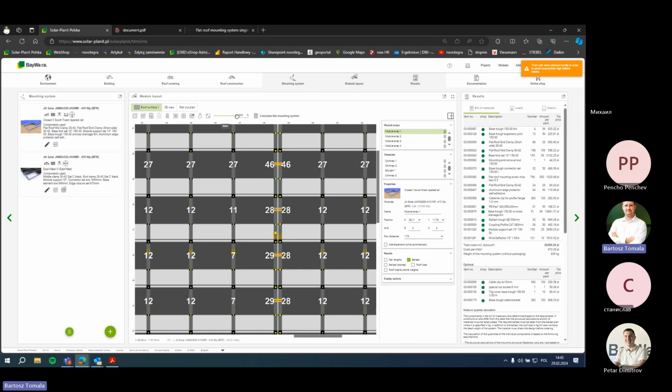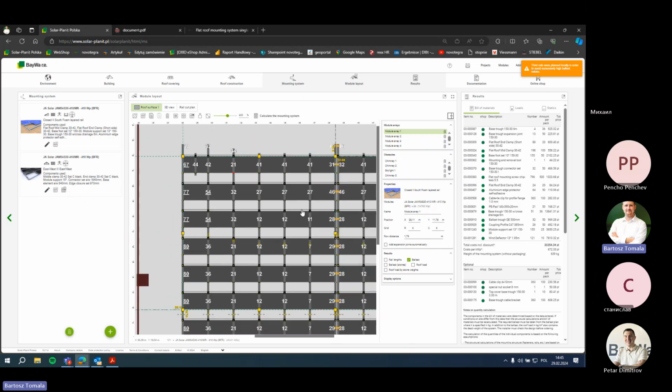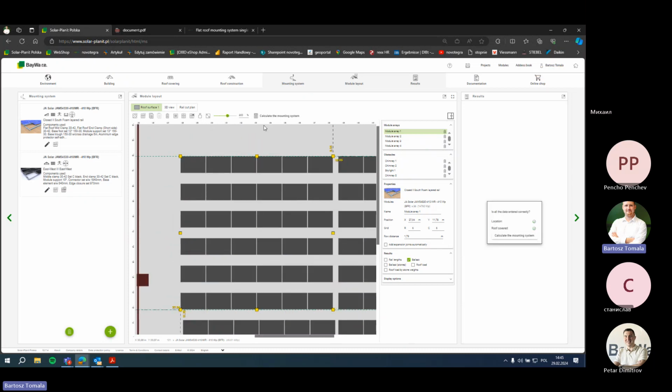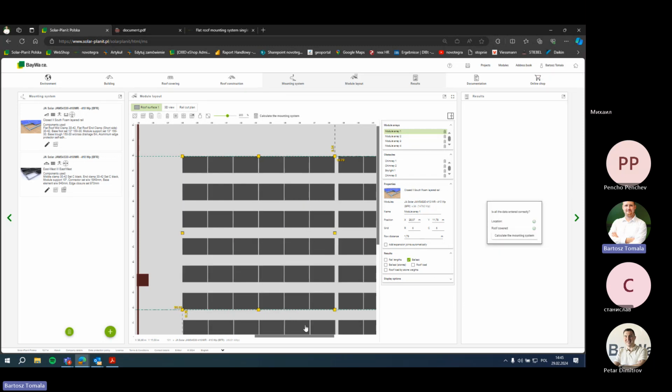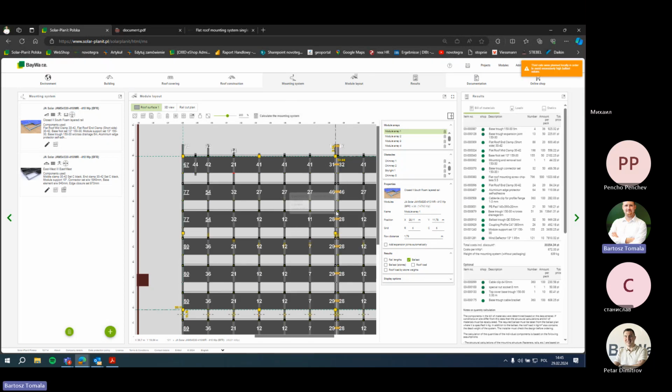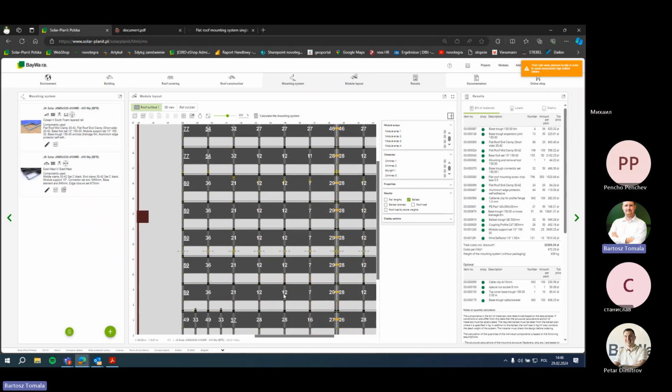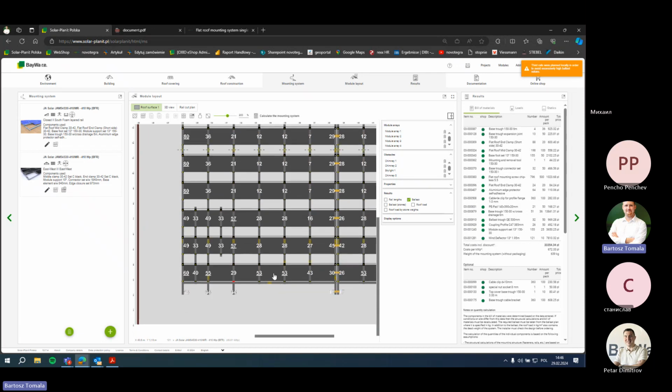It's also, of course, not a small ballast calculation, but if we just move a little bit, you can see the ballast changed, and these values are much higher. We have this third rail here, and there's almost 60 kilograms on each module. If we come back to this, we have much lower values needed to compensate the same installation. So it's important to be precise sometimes in this construction.